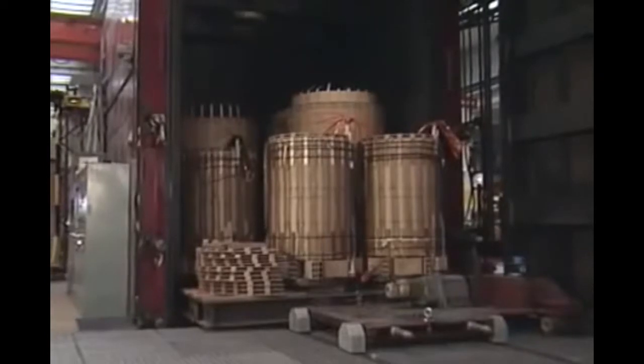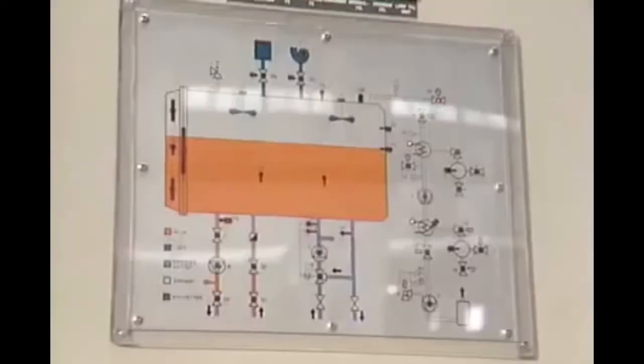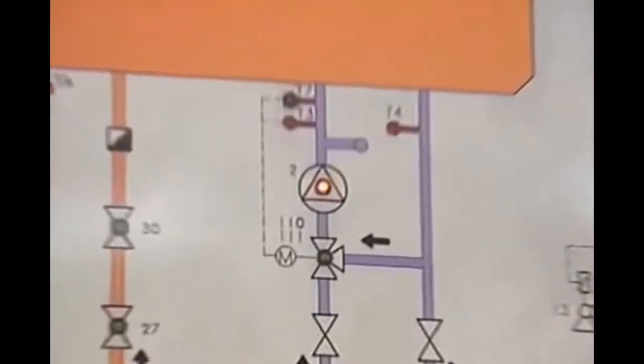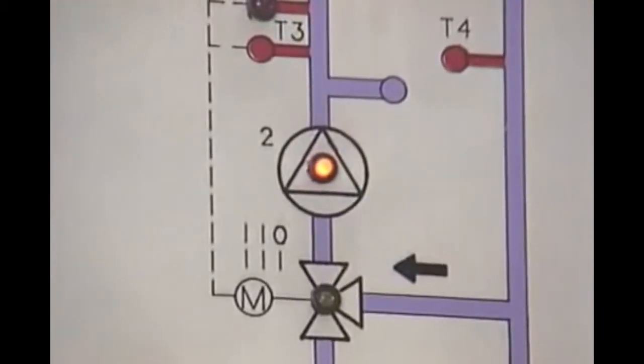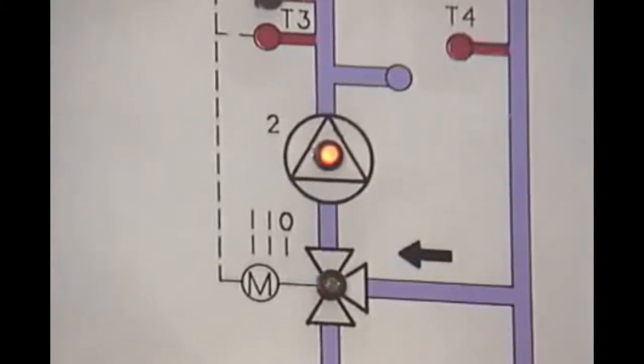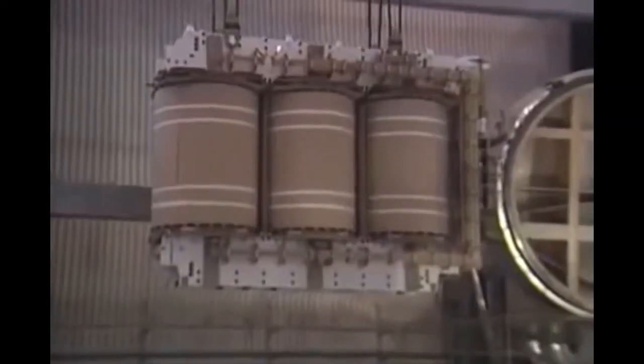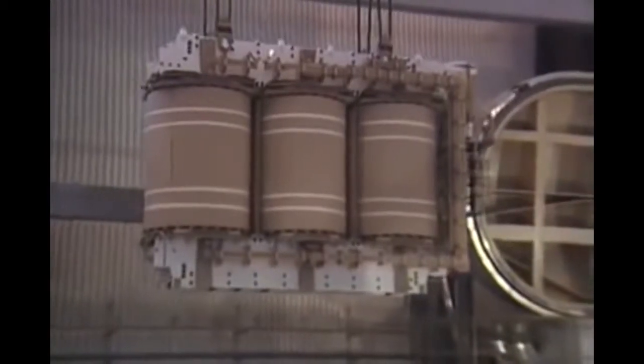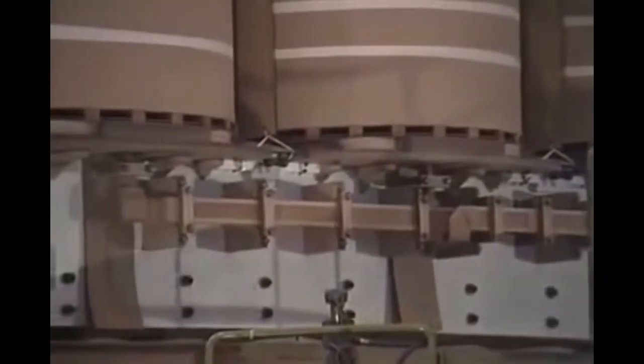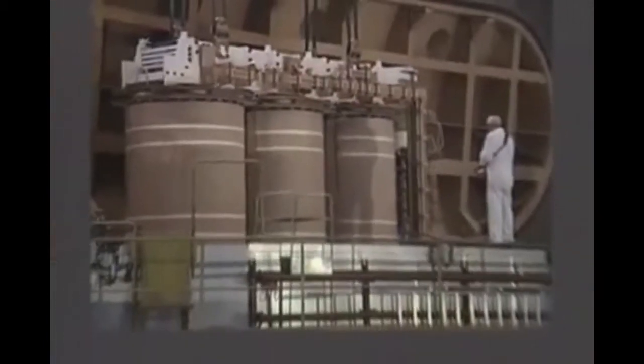Once the windings have been completed, the first of two main drying processes is carried out. ABB places great importance on these drying operations since excessive moisture in the active part can jeopardize transformer performance. Moisture degrades, for example, the dielectric strength of the main insulation system. The first drying process is performed on the complete winding without core. After assembling with the core, the entire active part is moved into a vapor phase drying chamber. Additional drying operations can be performed by ABB to meet any special customer requirements.